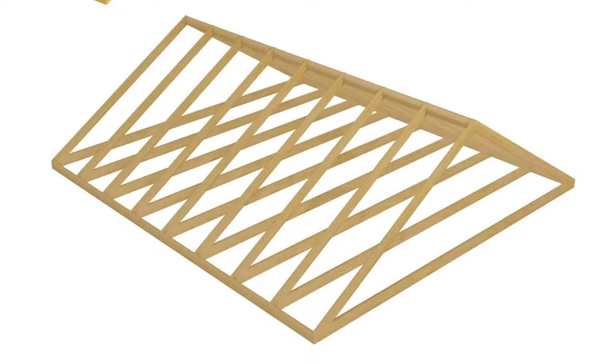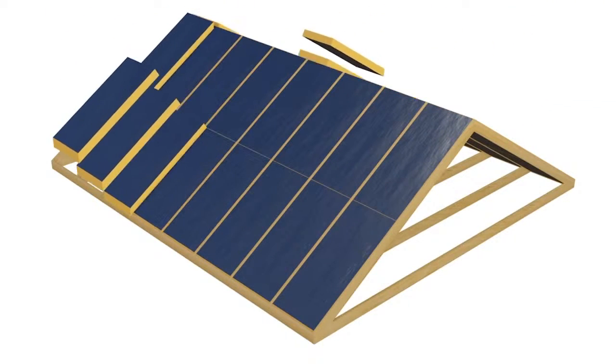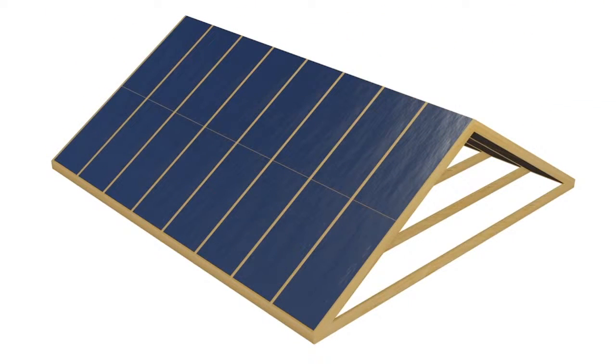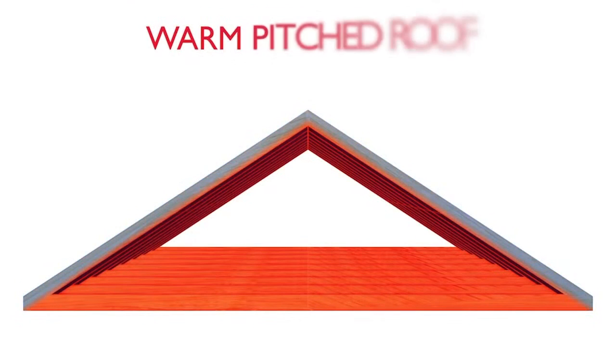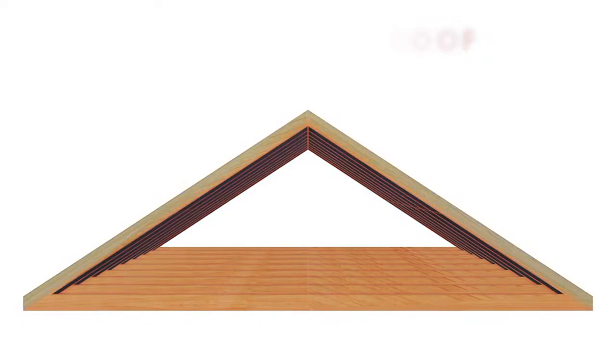Warm pitched roofs: in this roof type, the insulation follows the pitch of the roof, either between the structural members, over the top of the structure, or a combination of both. This leaves the enclosed space under the pitch as part of the heated envelope. In warm pitched roofs, it's much more common to see the use of rigid foam insulation, which tends to be more vapour and airtight than fibre insulation. This is primarily due to the thickness of insulation required to meet thermal standards. However, there's no fundamental reason permeable insulation types cannot be used.